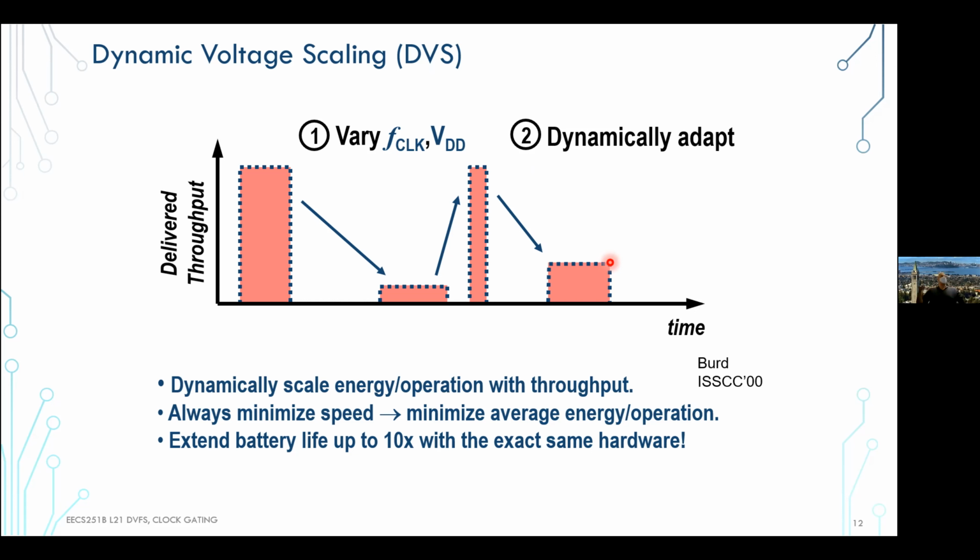And so people have tried all sorts of various schemes even for those blocks. The overhead of controlling, and how quickly you're switching the supplies, also matters. So we'll see some examples of that as well. But if you're doing it with reasonable separation, in these systems it could be seconds between tasks. We're not talking about nanosecond level switching or even microsecond level switching between tasks, because a lot of these supplies have decoupling cap, big capacitance that you don't want to drain too quickly. You want to ride that curve with slower time constants.